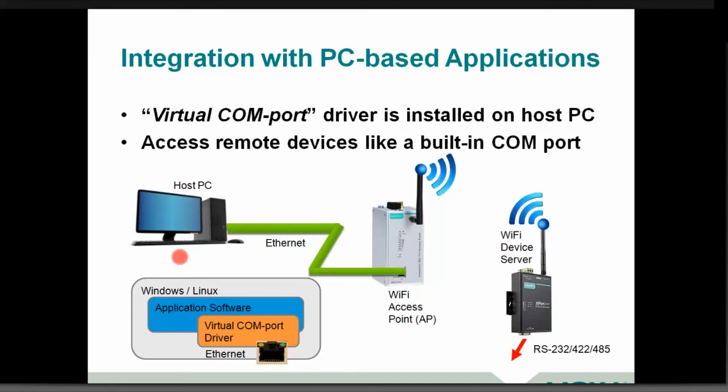And the magic here comes with a piece of software called a virtual COM port driver. That's a piece of software that gets installed onto your PC and allows that Ethernet attached asset out there over Wi-Fi to map into your application as a virtual COM port, right? So Ariana talked about these ubiquitous serial ports.